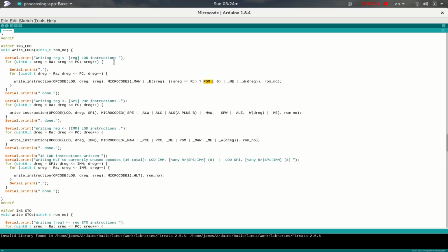And so if we ever want to read some data which is located in program memory and which we can't read simply by using immediate operands, or if it's not part of an instruction, we could, for example, have a function pointer table or something like this somewhere in program memory. Then there might be legitimate reasons to read data out of program memory. We can do that by making sure that we write the address into the C register, and then we can say the load instruction which is dereferencing the C register has this special meaning that it will in fact dereference program memory and not data memory. So that's the reason for this here.